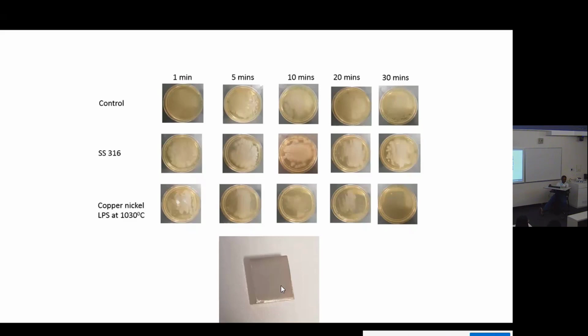So you would need to make your layer a different way, or at least there'll be different preparation techniques beforehand. So it's like photo etching and things like that, fairly common methods for lots of this stuff already, and you can use them in cold spray, which is part of that process. Yeah, you can use photopolymer plastic printers as well to do similar stuff to what you're talking about, which is very cool. So you can buy an aluminum film and put it on top of that too. You don't have to use cold spray.